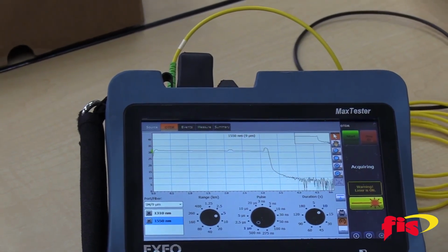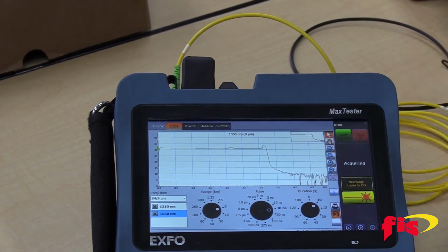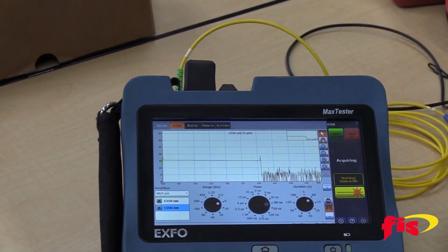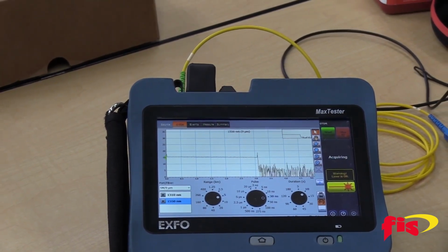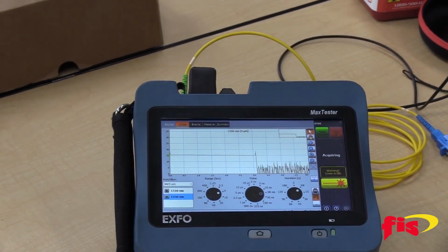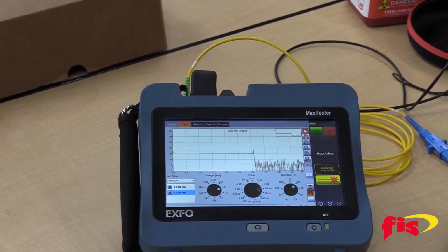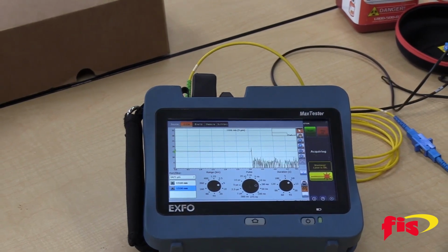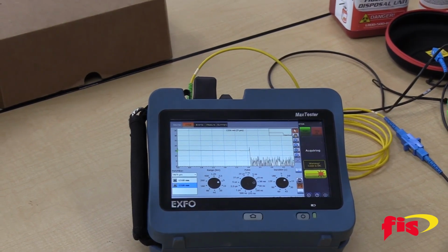So we always want a pulse box or a launch cable longer than our biggest dead zone. I always go 500 meters. Look, single mode fiber is about 8 cents a meter, so every 100 meters is going to add roughly $8. A couple extra 100 meters might cost you $24 more. I would prefer to have more to cover any long cables that I'm testing. Having them at 500 meters will cover all the short ones for sure, but if we ever come across a longer cable with longer dead zones, we're covered.